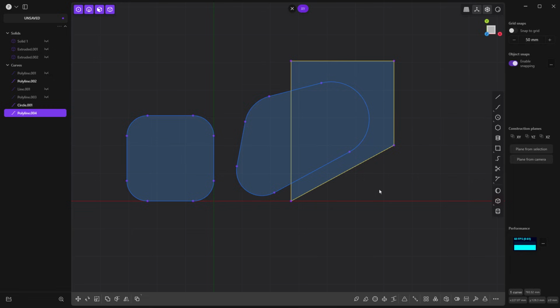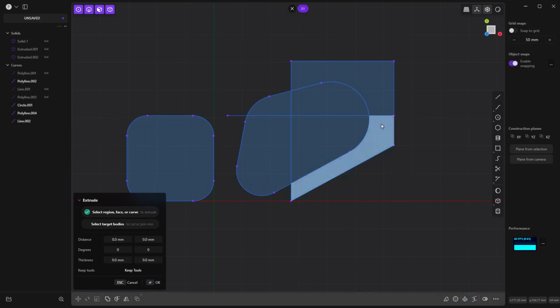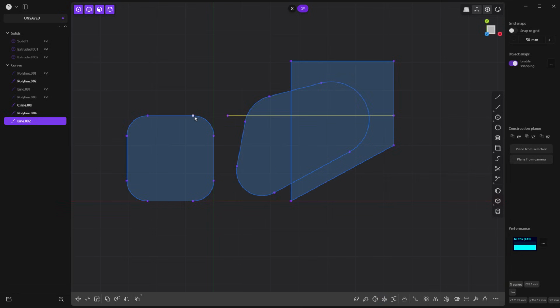So using those temporary projections is another way that we can make geometry reference something else, whether it's a tangency reference or a parallel or perpendicular reference or so on. And again, another example, let's say that I want it to be horizontal with this line. Tap shift, and now I've got this horizontal reference. I can intersect with this line here, right click, and again, this creates these closed profile regions that I can use. And now I know that this edge here is horizontal or collinear with that edge. In some cases you might find that you need to extend an edge or move it, and there are tools for that.